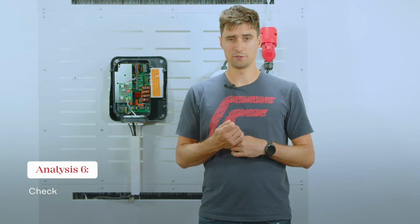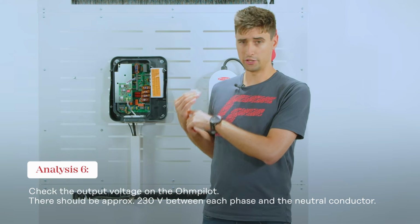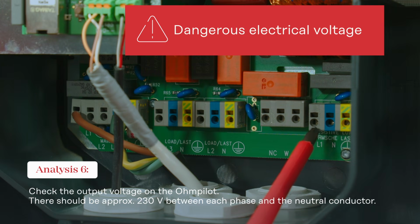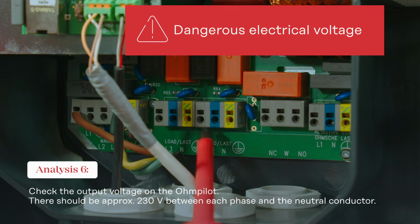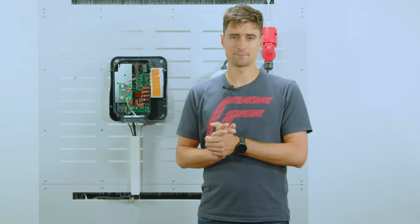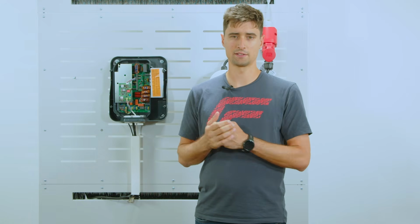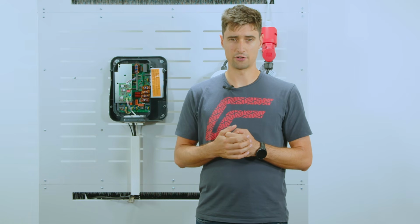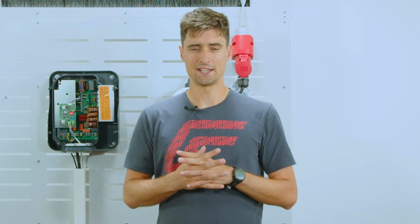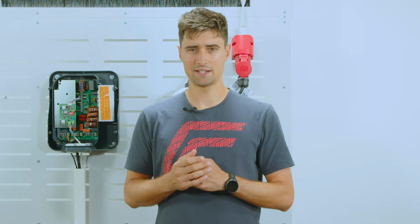One more thing you can do, you can check the output voltage on the Ohmpilot. So between neutral conductor and each phase, there should be 230 volts. If that is not the case, then it is very likely that the Ohmpilot has an error. And finally, I have 2 more hints for you, 2 more shortcuts that can help you finding a mistake quicker.